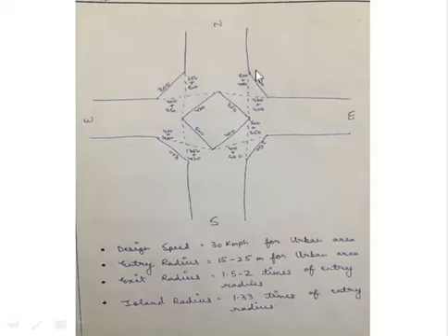So the traffic which is moving left is mentioned here as 300. The traffic which is going straight will follow this dotted path and leave the rotary by following this dotted path. So I've mentioned a traffic of 500 which is mentioned in the table here and here. The traffic which is going right will follow this path. Now it will come along the periphery of the rotary and will leave the rotary intersection following this path. So I have mentioned 400 here, 400 here and 400 here.